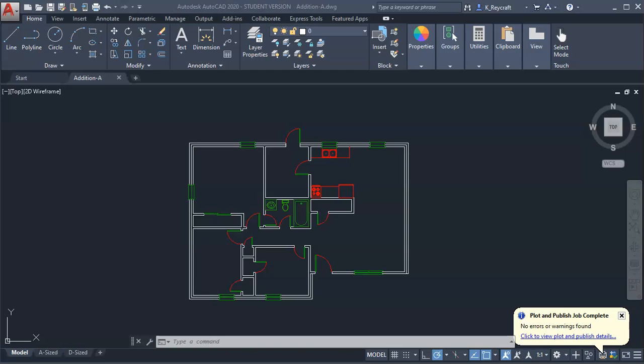The external referencing commands allow you to bring in, like it's a block, other drawings, other file formats as well. We're going to go through examples, but it allows you to bring them in so that you can see them and use them as a reference. We can later decide to combine or bind them to our drawing if we want, so that it's as if we used the insert block command. Or we may choose to detach, which means it will remove the inserted reference as if it had never been there, totally severing the connection between the two files.